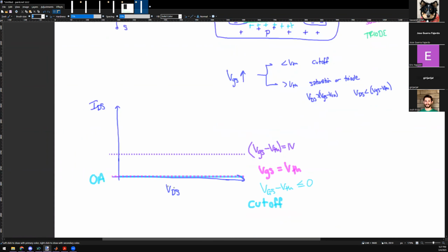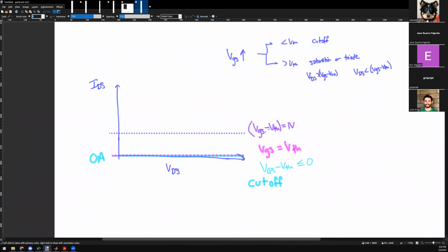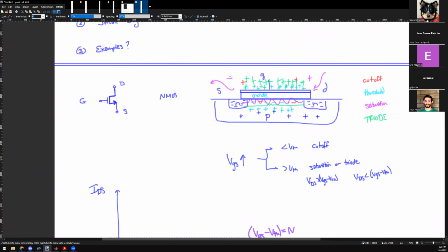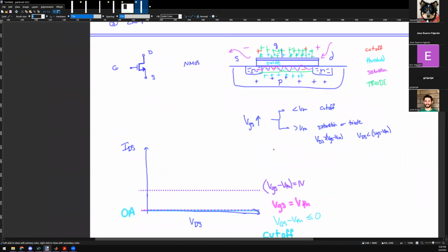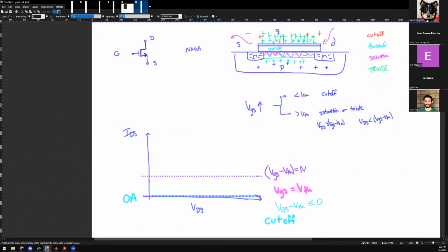And then I start increasing the VDS. At very, very high VDS, let's say I put 1 billion volts on this, no matter how much potential I apply, how much current can flow, and intuitively, what's the limit? The bar, right? So I have to start somewhere up here. No matter how much pressure you try to force through the straw, it just cannot do that flow, right? But eventually, when VDS gets smaller, what happens?